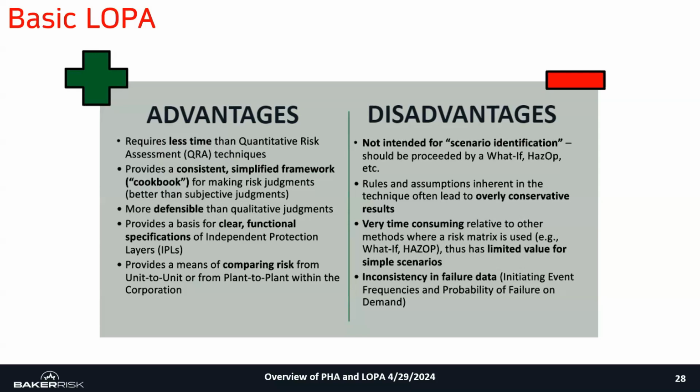Some disadvantages to LOPA. LOPA is not intended for scenario identification. That's really what your PHA should be doing, is identifying the scenarios. And then you take those scenarios identified in PHA and then, per your company requirements, take those to the LOPA process.